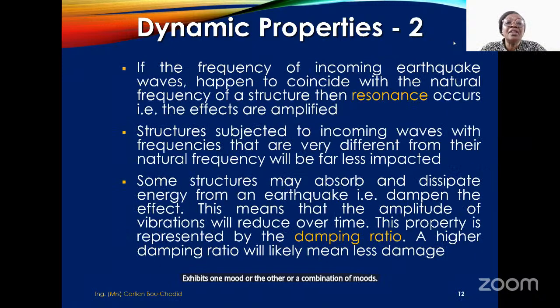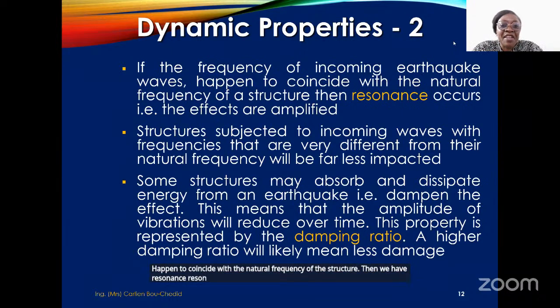Now, if the frequency of incoming earthquake waves happens to coincide with the natural frequency of the structure, then we have resonance, and we heard about this in the earlier lecture. This amplifies the effects of the earthquake on the structure and can lead to considerable damage.